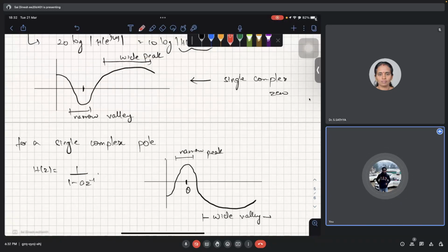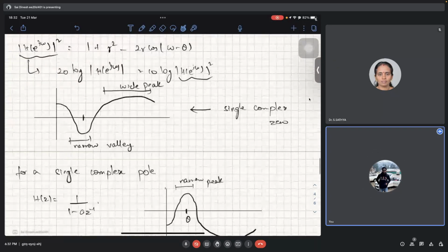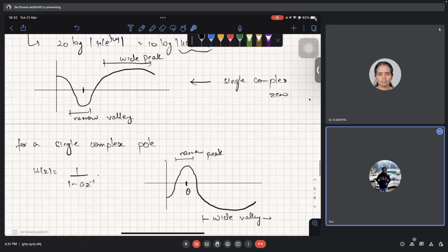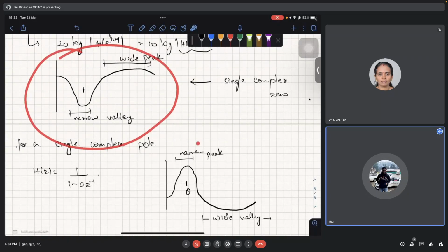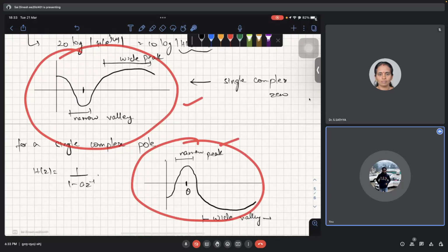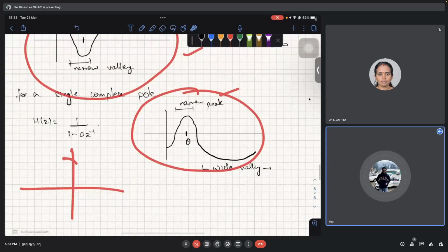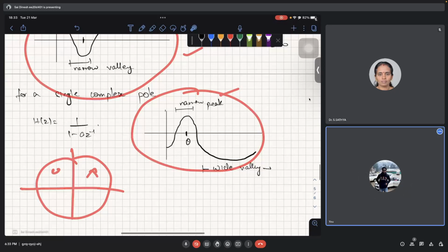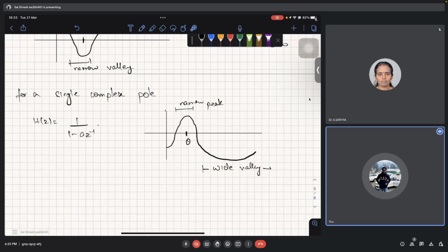So this is really important. The zeros and these poles are really important, because whenever we have a pole zero plot, due to the locations you can simply take the responses of the individual single pole or single zero systems, and then for the whole plot you just sum them up, and then you get a final magnitude response, right?